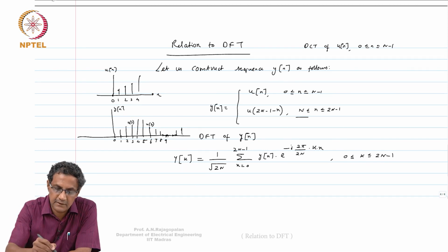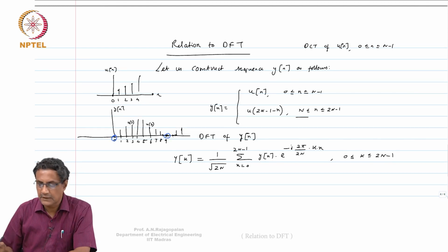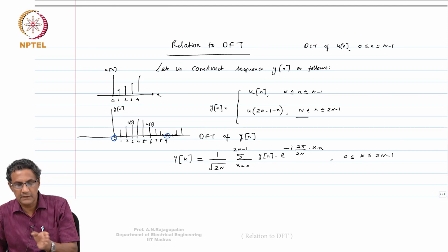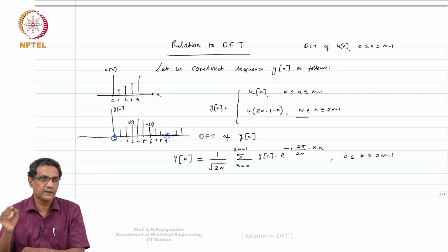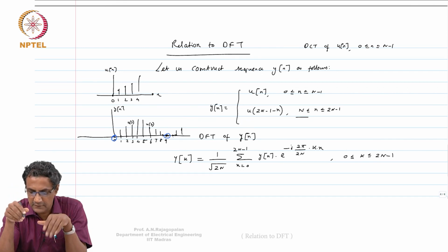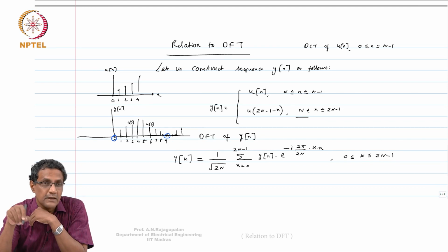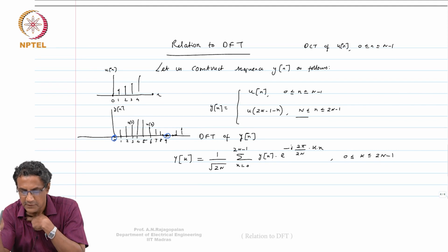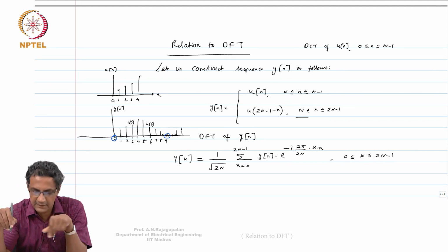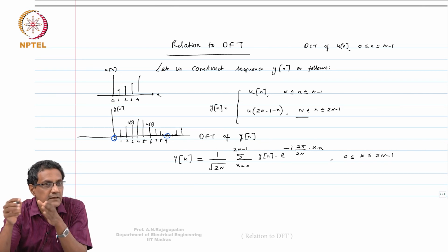So you see that you have made sure that the beginning and the end value of y[n] match, they're equal, and that is one way to see that this false jump you got otherwise is gone. So u[n] can be anything arbitrary, but once you extend it in this manner, it's clear that I get a y[n] sequence wherein I won't see this unnecessary jump happen.